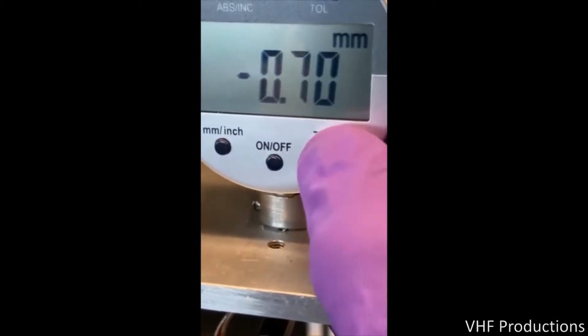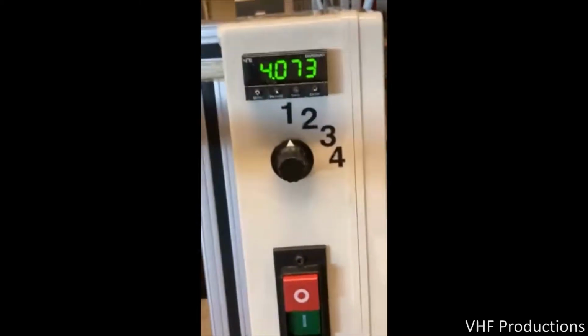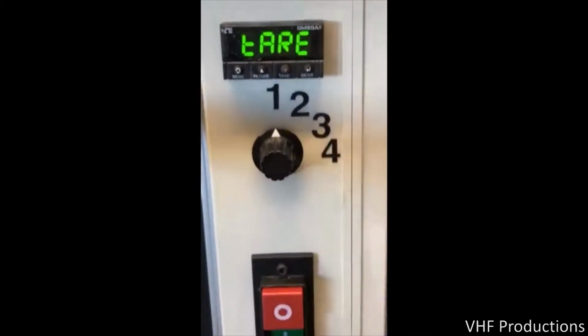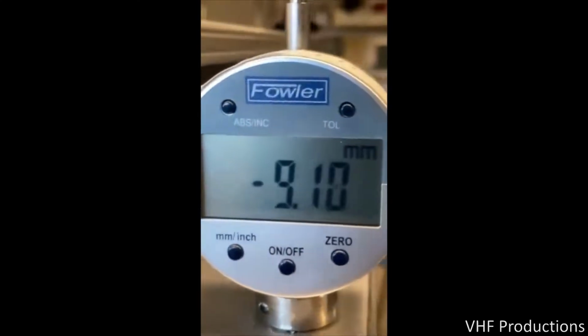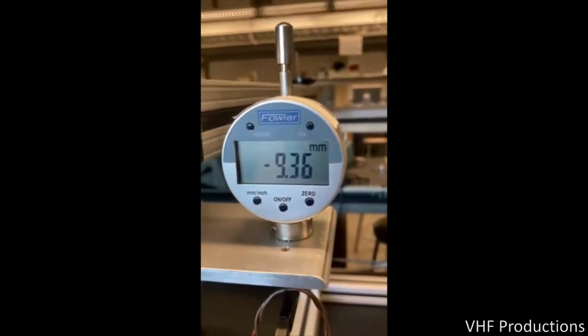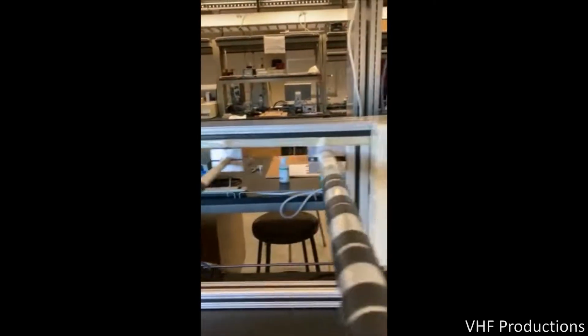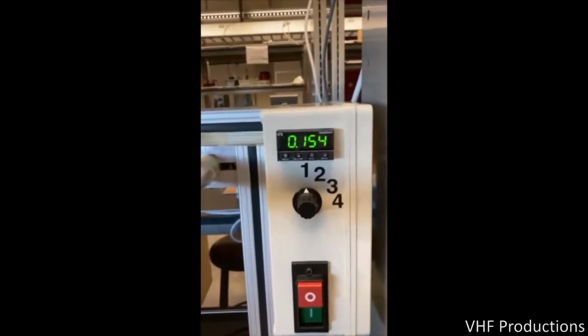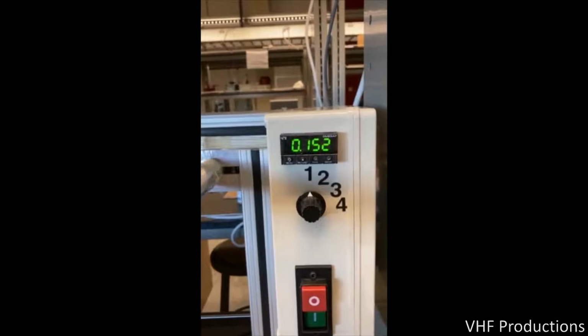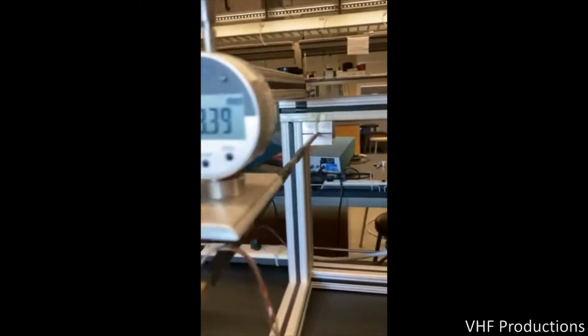And then we're going to see if the data is consistent with a material of a certain modulus. And that modulus is known for steel and aluminum, the two types of materials being used. We're going to do that for the different geometries at the different loading lengths, and the different geometries bring in different moments of inertia. And we'll see how that moment of inertia affects the deflection behavior of each beam.